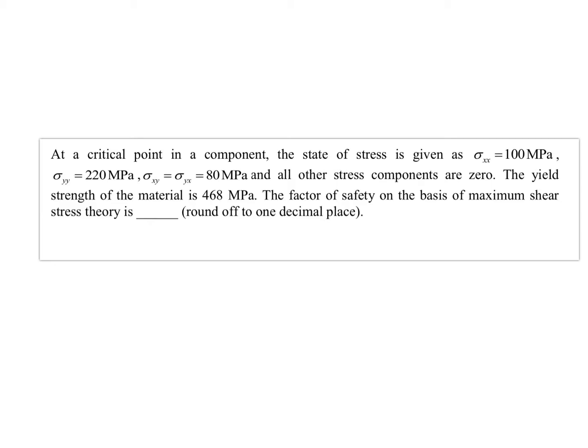They are asking us to figure out the factor of safety on basis of maximum shear stress theory. So the first question is: is this a general 3D state of stress problem, or can we reduce the problem from 3D to, let's say, 1D or 2D? Can we do that? The answer is yes, we can convert the problem from 3D to 2D because we have only in plane stresses, or this is equivalent to that of a plane stress condition. There is no stress component in the z direction.